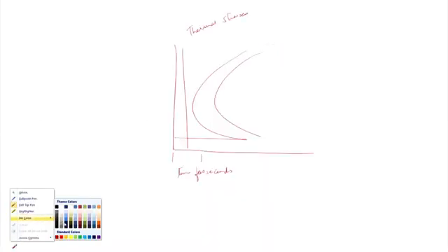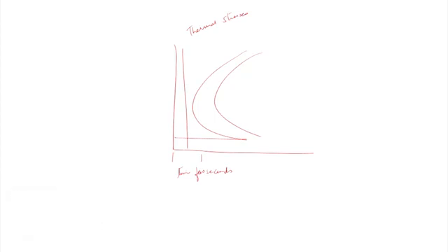So, by adding an alloying element, let me plot a new TTT curve in a different color. Suppose I add an alloying element. Now, when you have transformation from austenite to any other phase, there has to be redistribution of this alloying element. In austenite they may have different solubility, in ferrite they may have different solubility. So, the alloying element also has to redistribute between austenite and ferrite.